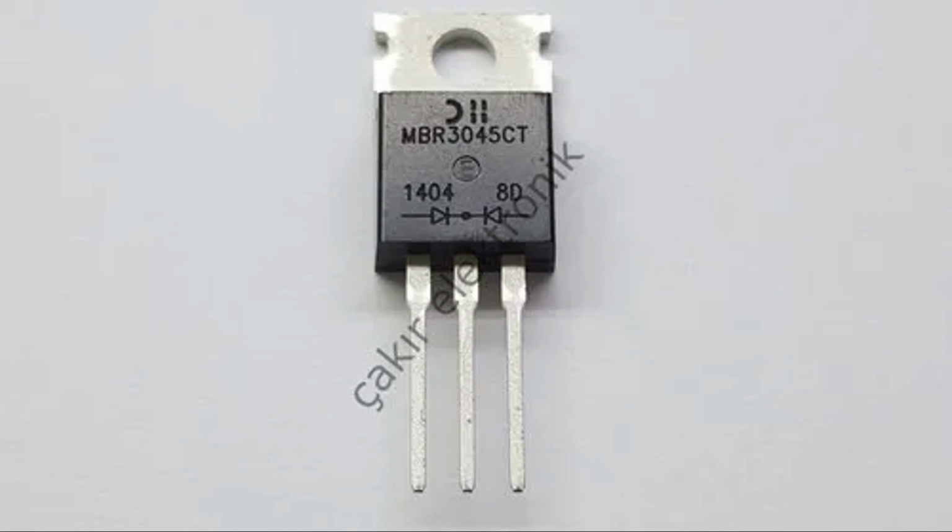To achieve lower reverse recovery times in diodes, designers employ various techniques, such as optimized junction design. Improving the physical structure of the diode's p-n junction can minimize charge storage and facilitate faster switching. Specialized materials. Using high-performance semiconductor materials with superior carrier mobility can lead to faster switching speeds. Temperature management. Controlling the temperature of the diode during operation can influence its reverse recovery time.